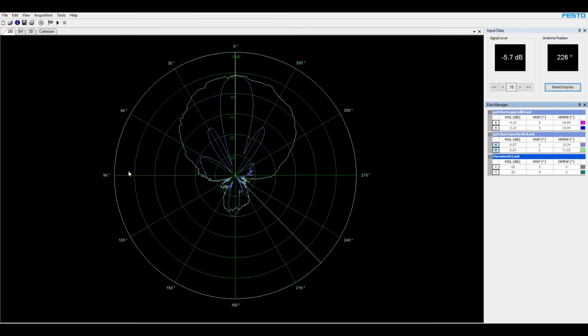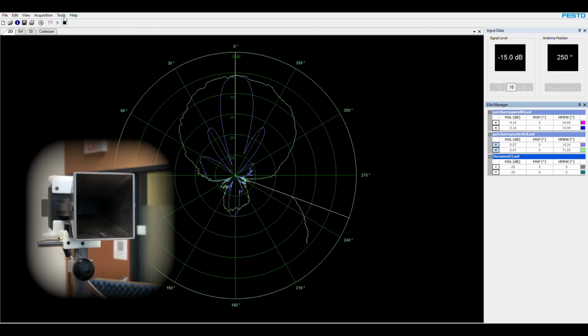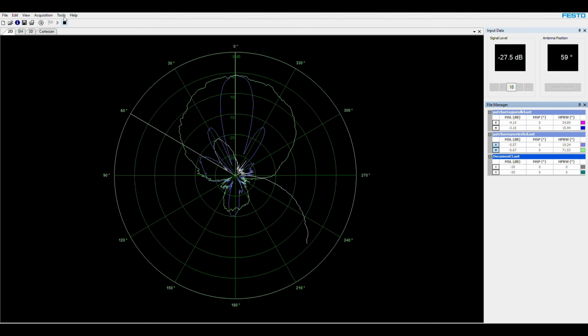As we noted earlier, we need to measure the gain of the series fed and parallel fed patch arrays. To this end, we're going to perform a measurement with an antenna whose gain we know. That's the small horn antenna, whose gain we know at the frequency of operation, 10.52. So let's start the measurement. We have the smaller horn antenna mounted in the H plane right now. The transmit and receive antennas are both vertically polarized. After I'm done with this measurement, you're going to see the maximum signal level of the small horn. Knowing that, and knowing the gain of the smaller horn antenna from the previous measurements, you would be able to calculate the gain of the series fed and parallel fed patch antenna.